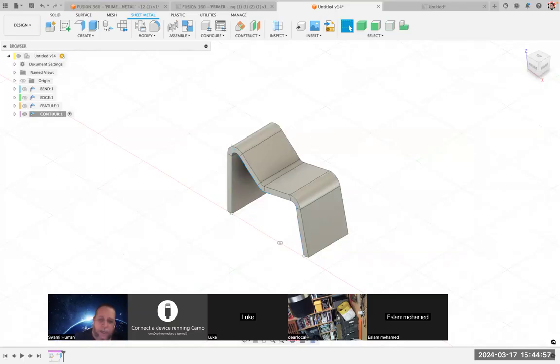So that's about the simplest. So if you have to make an initial face flange and then bend angle, bend angle, bend angle, it might be difficult to do those angles in a logical, easy, editable way. Whereas in the sketch, you could define your dimensions, angles, and lengths and such. So this will be more convenient in certain cases. So there you have it. That is all there was to that one. That was quick and easy. Let me go ahead and save, which brings us to the lofted flange, which is fancy and nice. So I'm going to hide that guy.